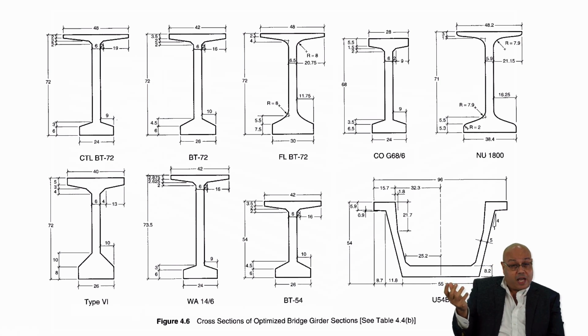So if you have 4,000 psi concrete, you can have around 477 psi as far as the modulus of rupture, or the tensile capacity of the concrete. So that will give you a very small moment capacity.